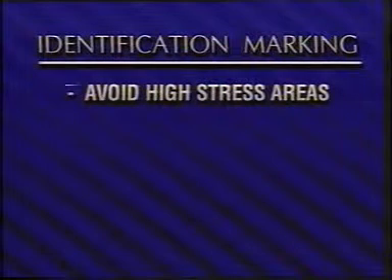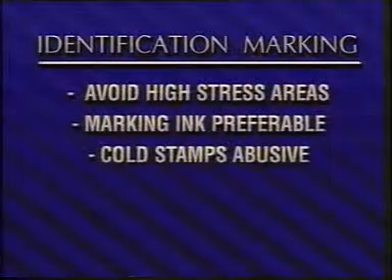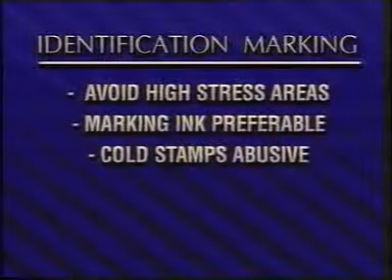For castings and forgings, raised letters introduced in the dies or molds are preferred to indented stamps. For marks on machined surfaces, a marking ink is preferable to using an electric etching pencil or vibrating mechanical engraver. A cold steel stamp is probably the most abusive to the steel.